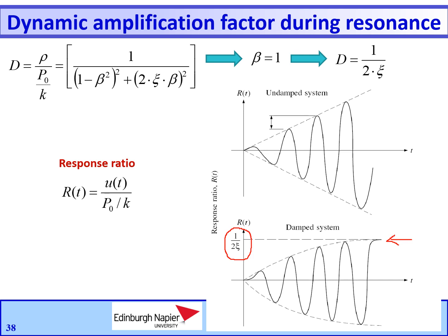As we can see, the deformation varies with time as a cosine function, with its amplitude increasing with time according to the envelope function shown by the dashed lines. Obviously, the amplitude of the steady-state deformation of a system to a harmonic force with omega equal to the natural frequency of the system, and the rate at which steady state is attained, is strongly influenced by damping.